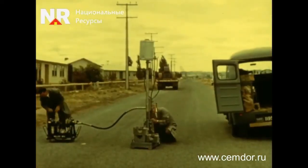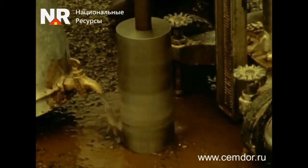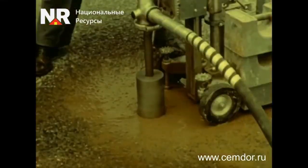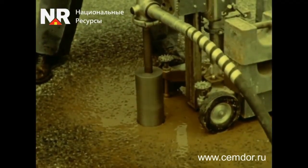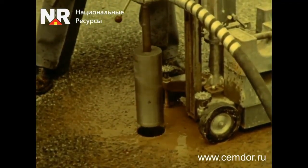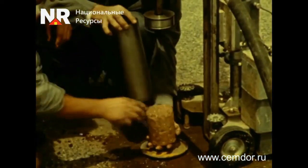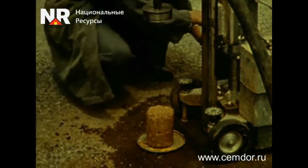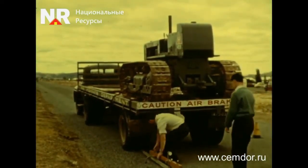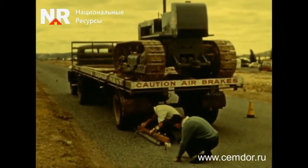A sample taken from the fully completed soil cement structural layer using a core sampler is examined to confirm that the soil cement mixture will gain strength over the years and that its safety margin will also increase, which will allow the road to maintain its load-bearing capacity despite increasing traffic intensity. The flexural strength limit of the soil cement roadbed is determined by on-site testing using a long base lever deflectometer with the static loading method.